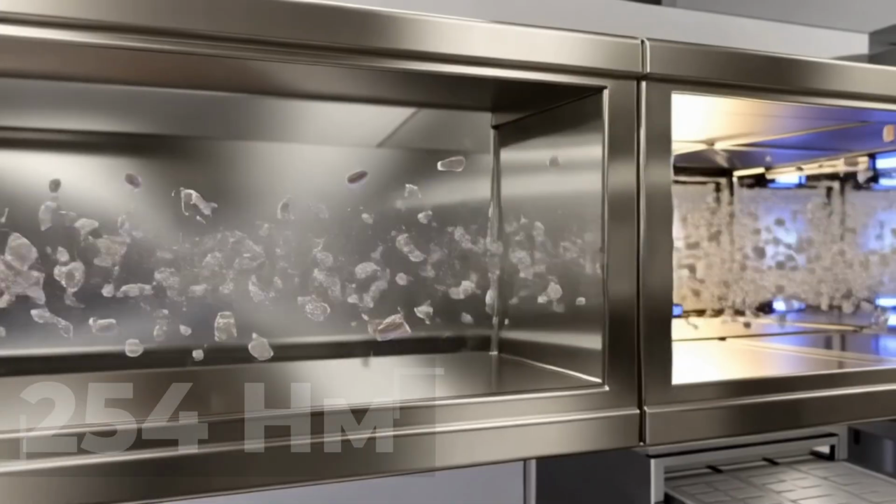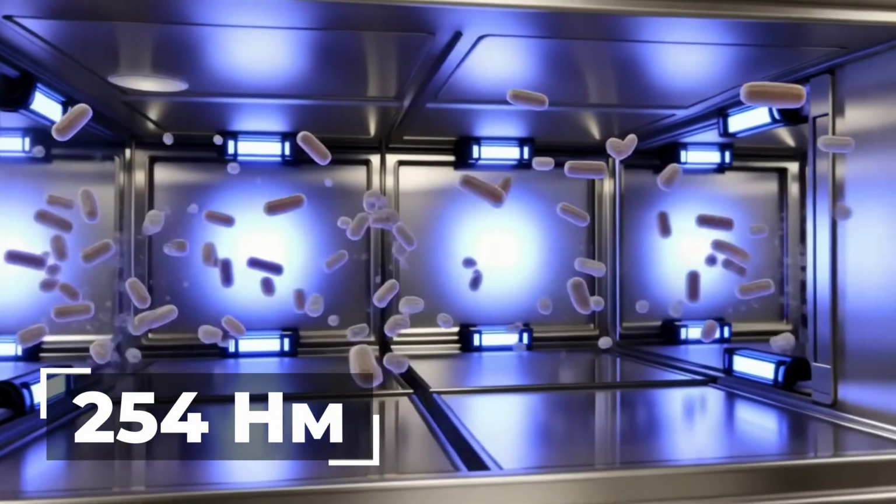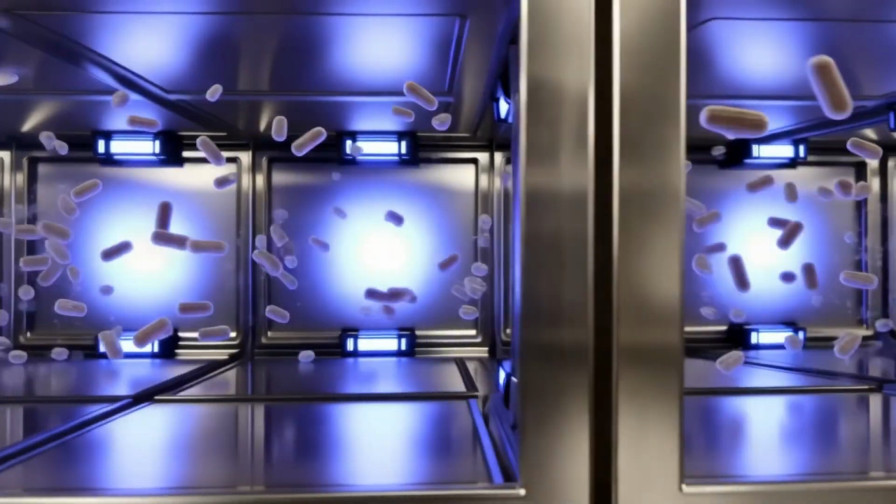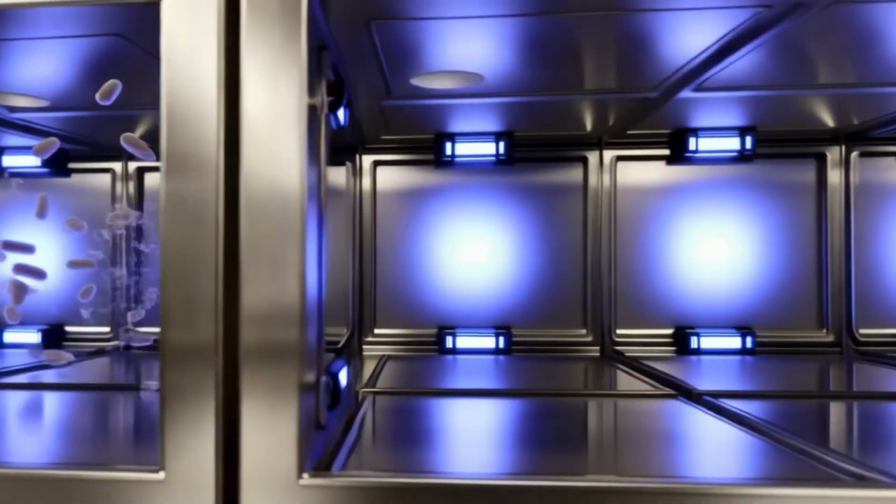Bactericidal sections are modules with built-in UV lamps that are installed in a ventilation system, giving it the ability to supply rooms not only with fresh air, but also with air purified of microorganisms. With their 254 nanometer wavelength radiation, ultraviolet lamps neutralize bacteria, viruses, fungal spores, and mold at the DNA level, preventing their reproduction and ensuring bacteriological safety in all rooms.